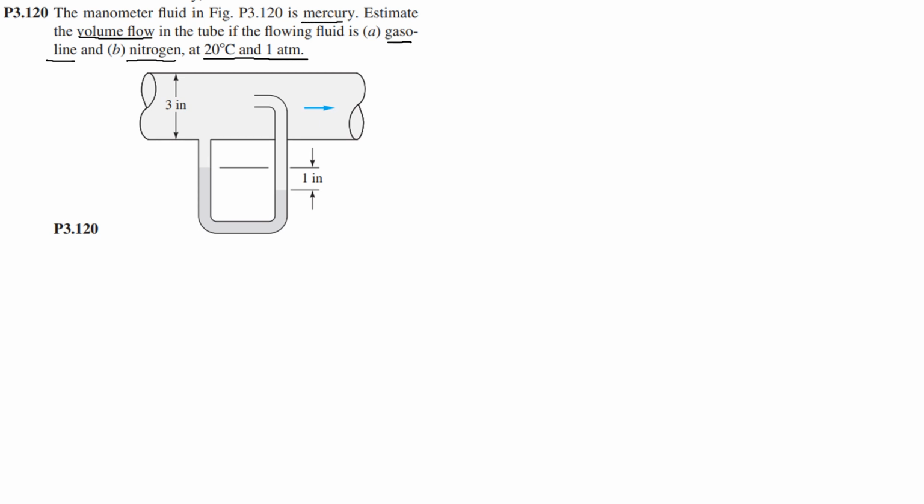This is the manometer and this is the mercury inside this manometer. This manometer, as you remember, is used to determine the differential pressure between these 2 points. This point was used in the previous figure to measure the static pressure, as you remember, and this point was used to measure the total pressure, because here the fluid is brought to rest, so that velocity conversion to total pressure occurs at this point.